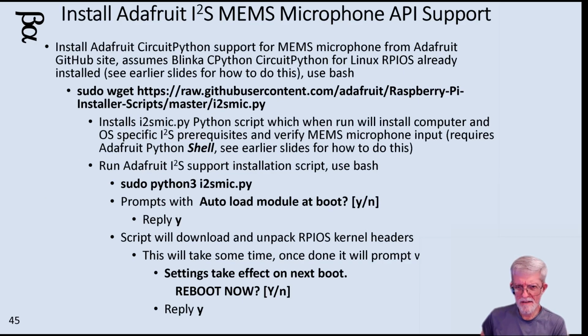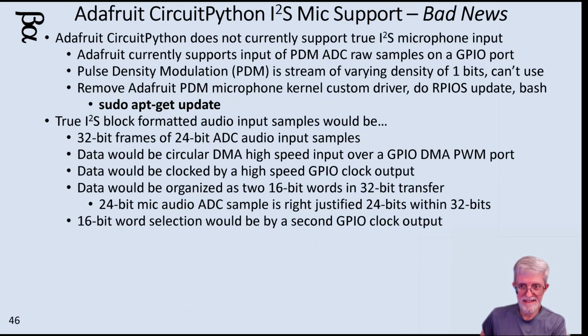Now, this one was kind of a red herring. You had to install the Adafruit MEMS microphone support. It turns out the Adafruit MEMS microphone does not really use the I2S interface. It uses something called PDM. So I went through this and then had to back it out. And that's what, here, look, we're backing it out. The interface is PDM, it's not I2S.